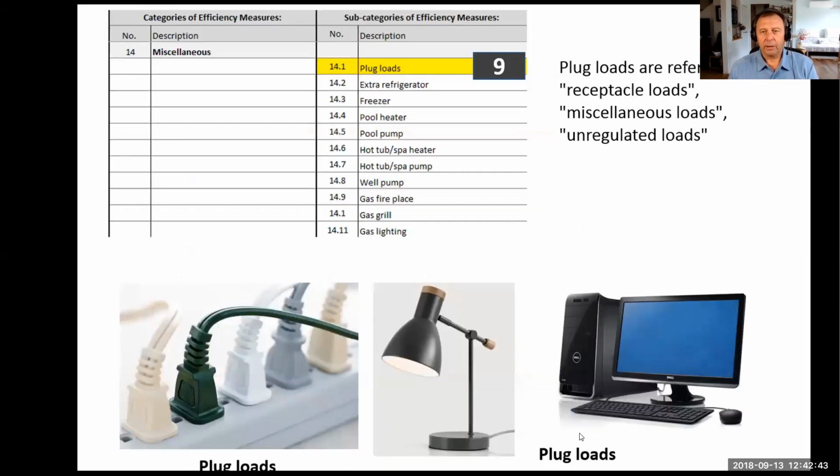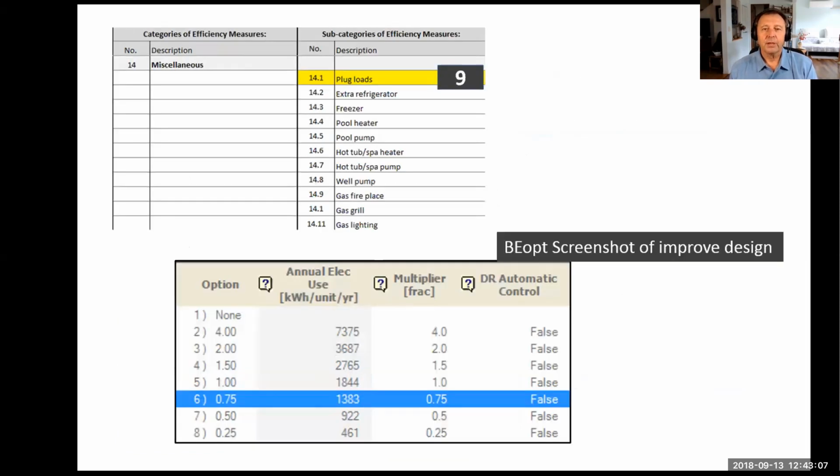The next one is the plug loads. You will see that in BEopt they give default values which are based on standards. And the standards came from long research. It can also be regional, but this is usually how people behave. But we always have the possibility of changing it by putting some kind of a fudge factor in there. Here you see we have the multiplier factor, which is the multiplier from the standard. The standard would be 1.0.